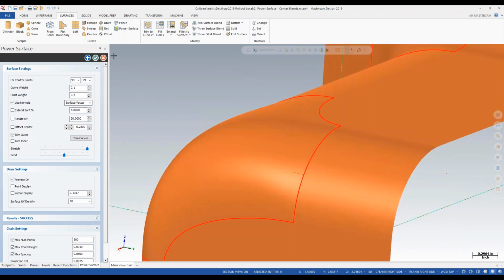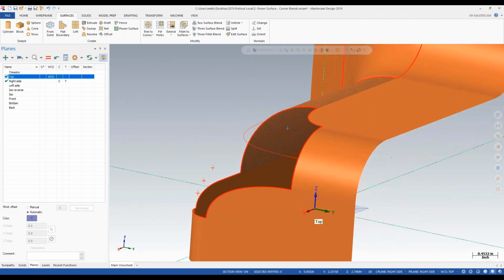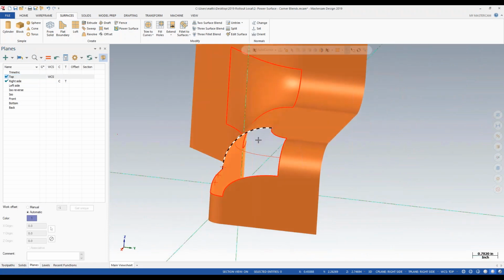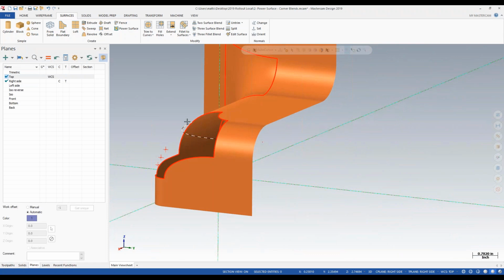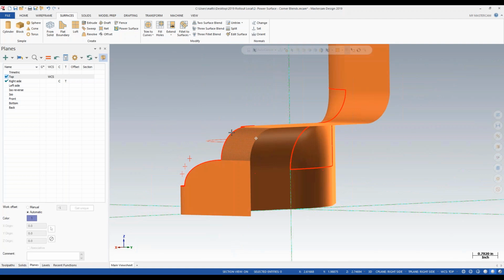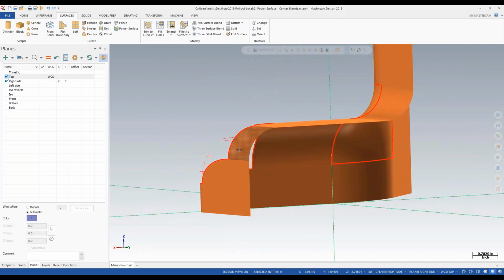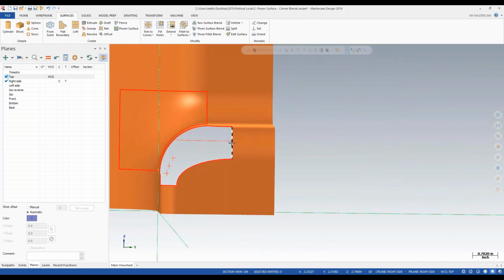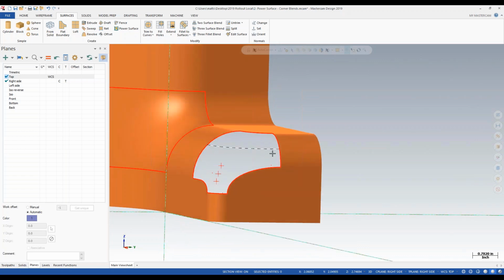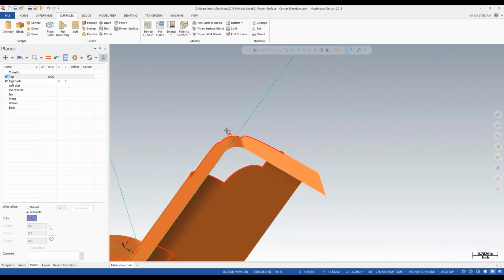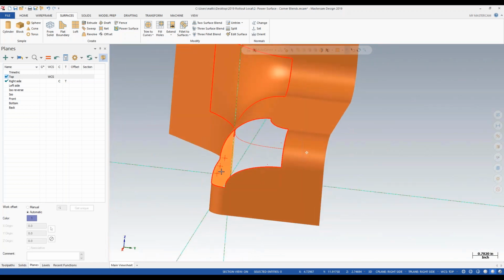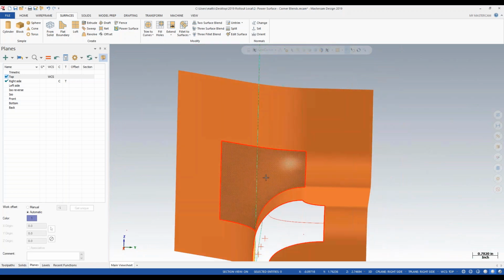But my other option, and the nice part about this is it's easy to use, is I can essentially draw any additional control I want. So I can have a line here that I drew that's maybe an intersecting point. This is essentially the center of this radius over here. I want to make sure that this cap I'm putting on matches up that radius around the corner. And these points here, if I go into this view, were created on the center of this radius via an arc or spline command.